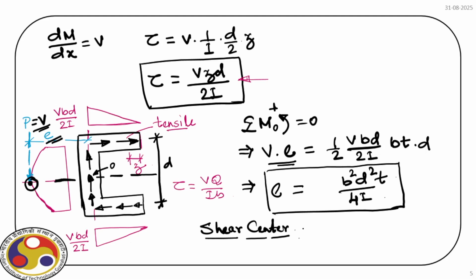This is very important. So when we design a section, we have to be careful for asymmetric sections, because the shear force must pass through the shear center, and if it passes through the shear center, then that will not cause any rotation at the section level. Otherwise, even the bending will cause a rotation because of the asymmetry at the section level we have. Right. So what we have defined is shear center for an asymmetric section.